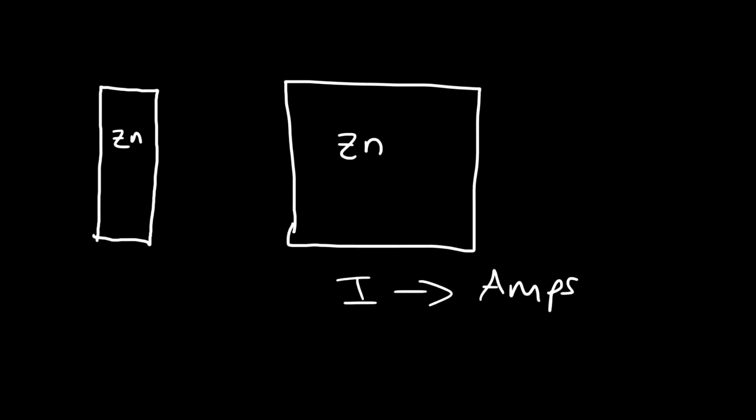the circuit. And so if you can increase the surface area of the electrodes, what happens is you decrease the internal resistance of the battery, and so the current delivered by the battery goes up. Now if you have a metal electrode, it may not be practical to increase the area of that.